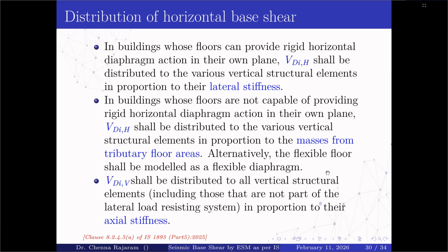Now, after distributing the base shear onto floors, how is the force distributed onto the frame elements? For buildings whose floors can provide rigid horizontal diaphragm action in their own plane, V_i^DH shall be distributed to the various vertical structural elements in proportion to their lateral stiffness.